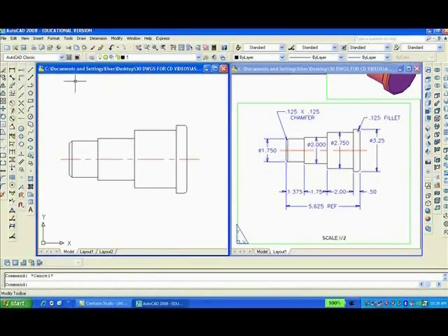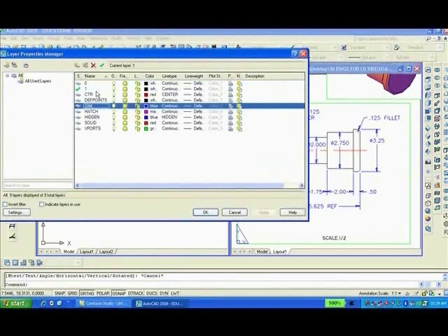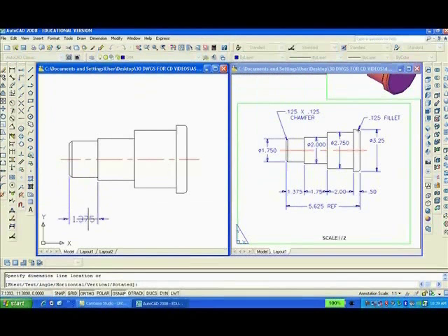It looks pretty good. So now I'm in a position to start dimensioning. I'll go to linear dimension, and I'll pick from here to here, 1.375. Wrong, because I ought to change the layer and make the dim layer current. And so I'll go to dimension again, start it over here to here, and bring it down like that. Hit enter to repeat the command. Go from here to here, enter to repeat from here to here. Well, I'll put it like that. Doesn't really matter. And then enter to repeat the command from here to there.